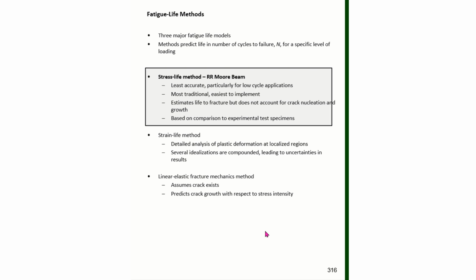Then the last method, the linear elastic fracture mechanics method, assumes a crack exists and then predicts the crack growth with respect to what we call a stress intensity factor. And this is the most accurate method, but it is very mathematical and complex to apply to a practical problem. So we will focus again on the stress life method, which is based on the RR Moore beam approach.